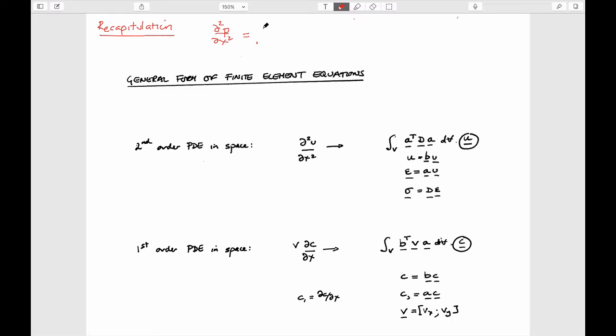And it looks something like this. Hydraulic conductivity, specific storage. Let me write it the way we've done it. We've written it in head, of course, haven't we? So let's go back. I'm just going to swap out that P with H. So we've written it in terms of hydraulic head, in terms of specific storage and the rate of change of head with respect to time, and the hydraulic conductivity. This would be what it would look like in 1D.